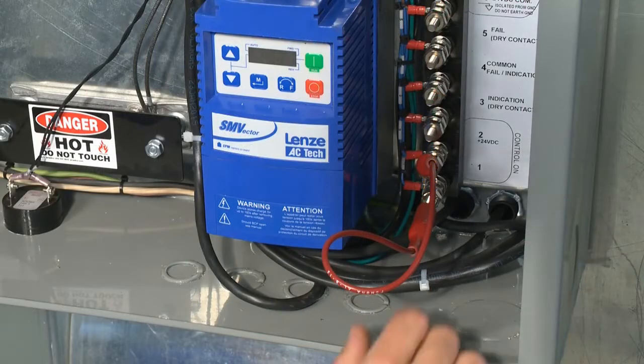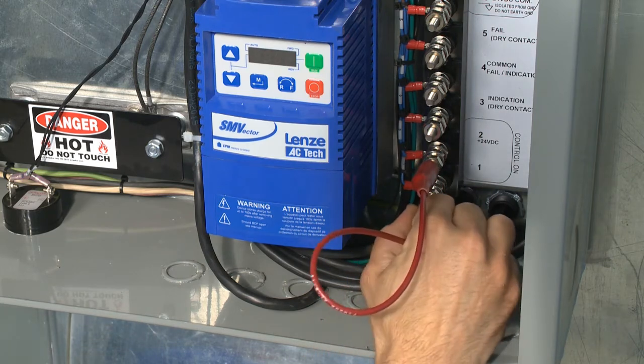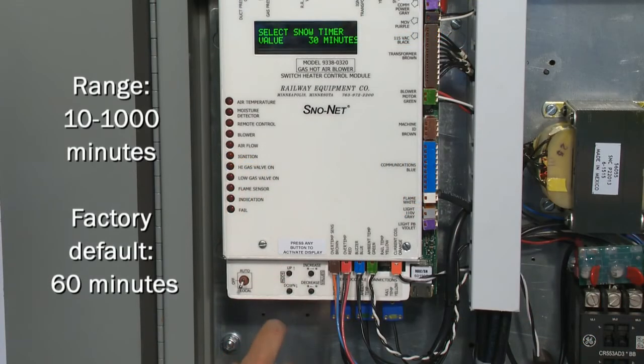Restart the unit by removing the contact closure between terminal posts 1 and 2, and then reinstall it. Select Snow Timer value controls how long the system will run after snow is no longer detected. The snow time starts counting down when the moisture detector no longer sees snow.